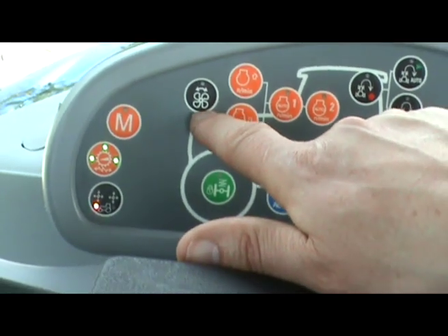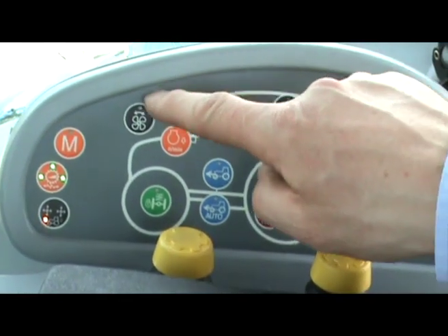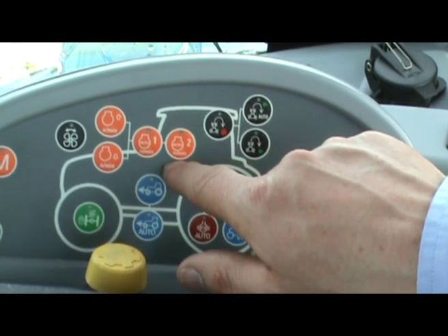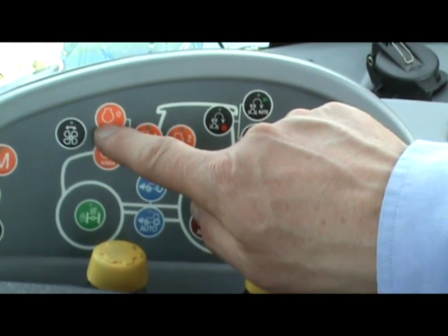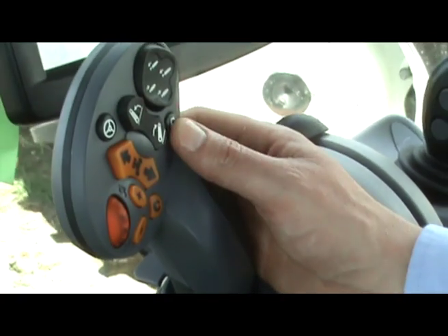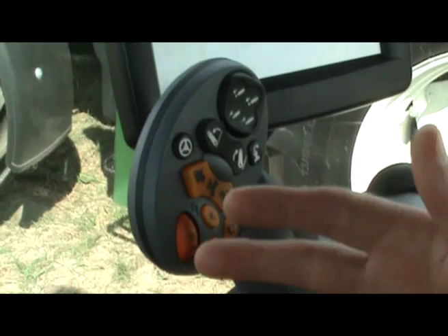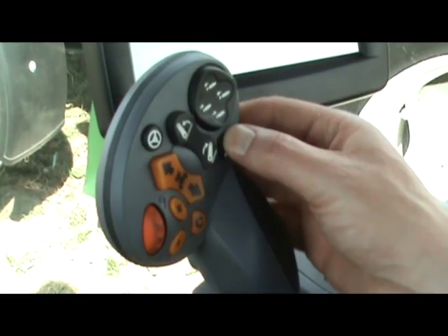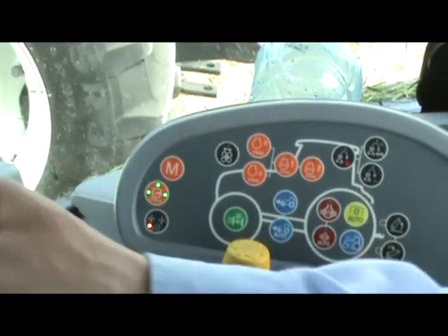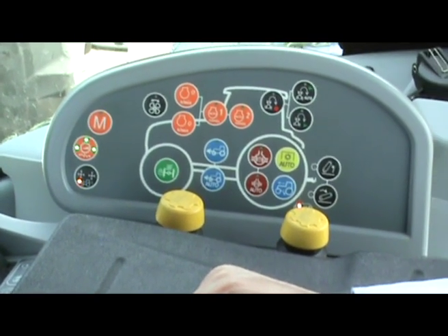Reversible cooling fan if it's fitted, and pressing that reverses the vanes on the cooling fan to clean the radiator out. These orange controls control the engine speed management. You've got 2 engine memories you can set just by revving up and down on here, and then using the button on the command grip here, pressing that will toggle between the 2 memories. So for example, one memory could be a working speed, come to the headland, press the button, changes to memory 2, which is going to be your headland turn speed, back into work, press it again and it'll go back to your working speed, so there's no need to keep adjusting the throttle settings.